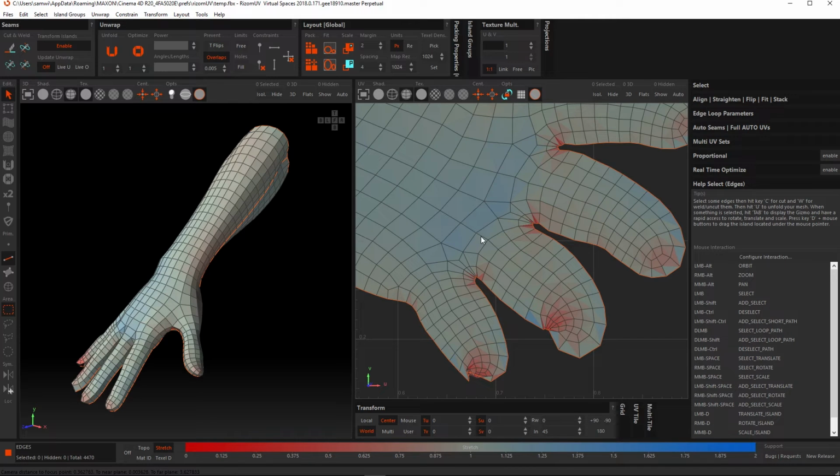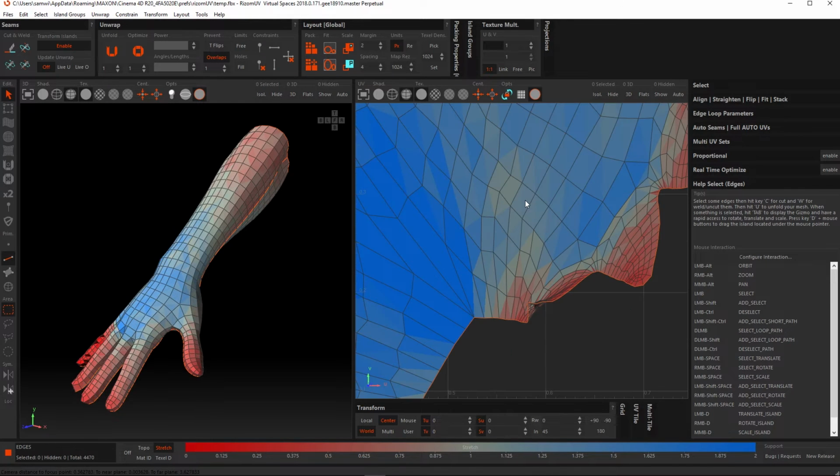Care should be taken when using the room space value, as large values can cause problems with the UV mesh. So if I give our room space a value of 1 and then unfold, you can see that our UVs are suffering from undue stretching, as shown by our stretch map colours, and if we look closely, also flipped UVs, which brings me nicely to our next setting.